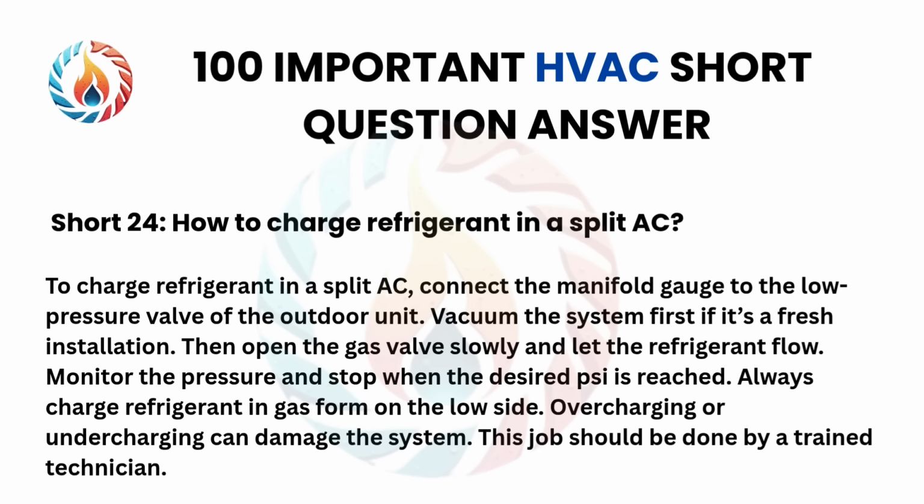Then open the gas valve slowly and let the refrigerant flow. Monitor the pressure and stop when the desired PSI is reached. Always charge refrigerant in gas form on the low side. Overcharging or undercharging can damage the system. This job should be done by a trained technician.